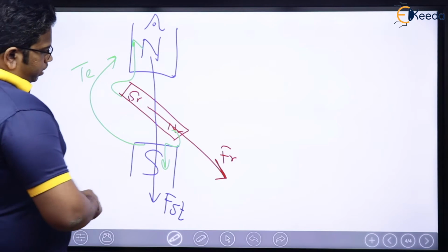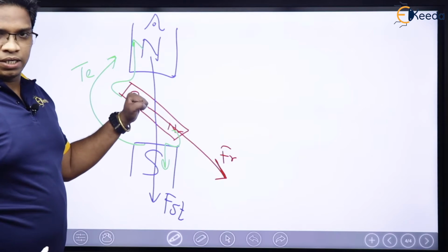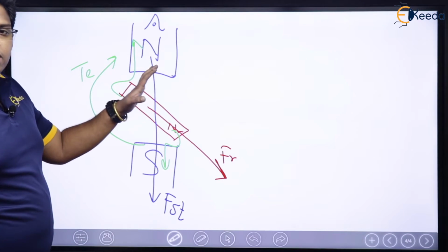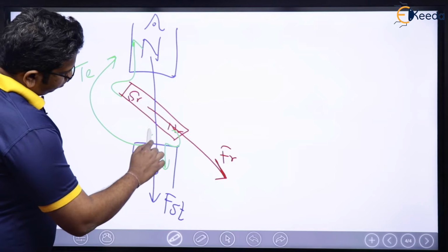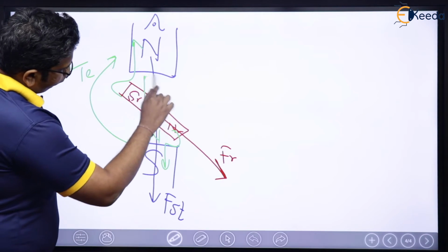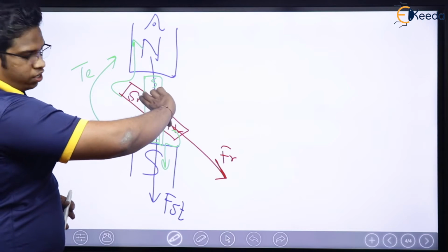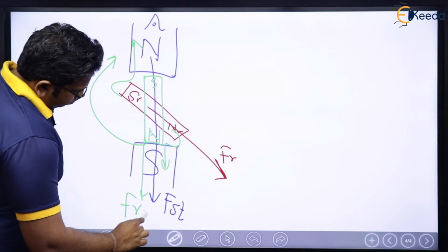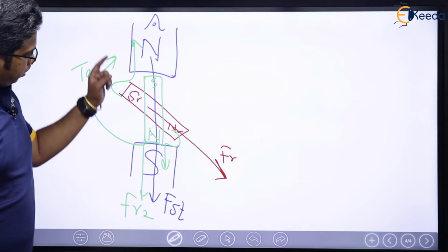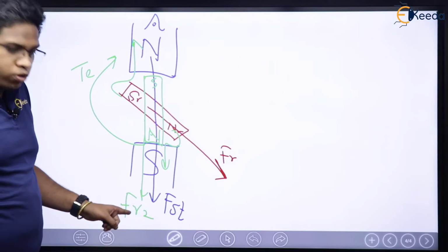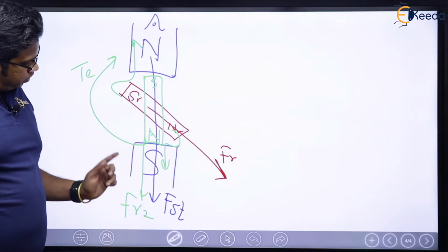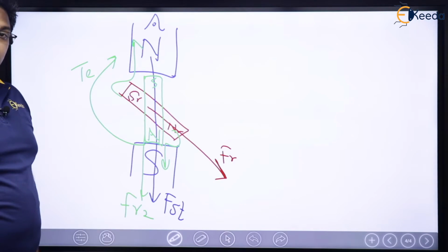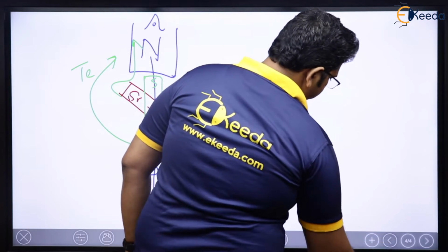And we already know that if, for example, it is a motor, I am holding it like this. Torque is in this direction, which means I will have a twisting moment like this. Now I am releasing my hand. The moment I release it, this N will come here, and this south will go up like this. This rotor will get shifted like this. Now here, if you see, angle is going to be 0. Let us say it is FR2. Here the angle between the stator MMF and my rotor MMF is 0. In this case, will there be torque? No torque, because it is aligned, magnetically locked. Moral of the story.